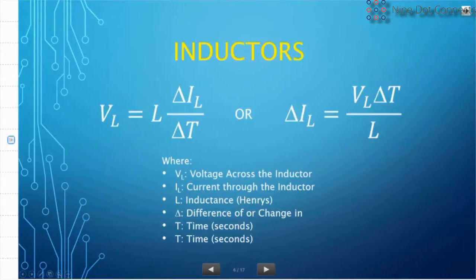So the basics of inductors, I'm sure you're familiar with. We all know that we take a resistor, and if you put a voltage across it, the voltage causes a current. It's a direct linear relationship. We tend to also know that if we squirt current into a capacitor, the capacitor tends to charge up. The inductor is very similar to a capacitor, but it works the other way. If you apply voltage to an inductor, then the current will ramp up.